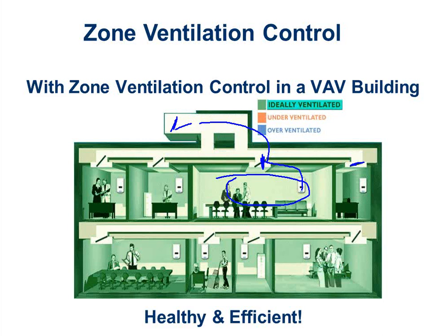Andy asks, does that imply that a VAV damper could go to 0 CFM when there's no temp load or vent load? You could set it up that way, Andy, but you're not going to want to do that because we still need some ventilation for taking care of the non-people related sources in the building, like off-gassing of carpets and so forth. So we will have a minimum on there.